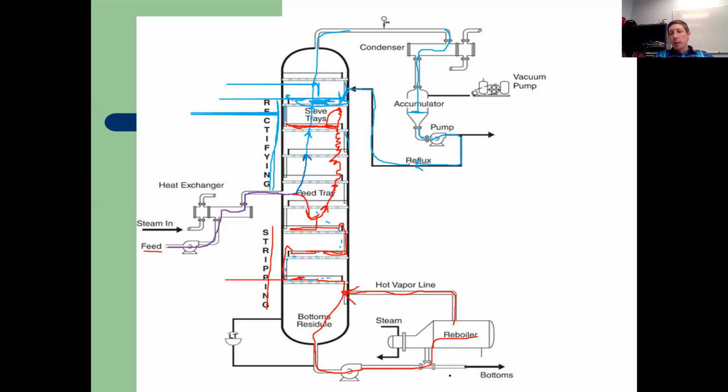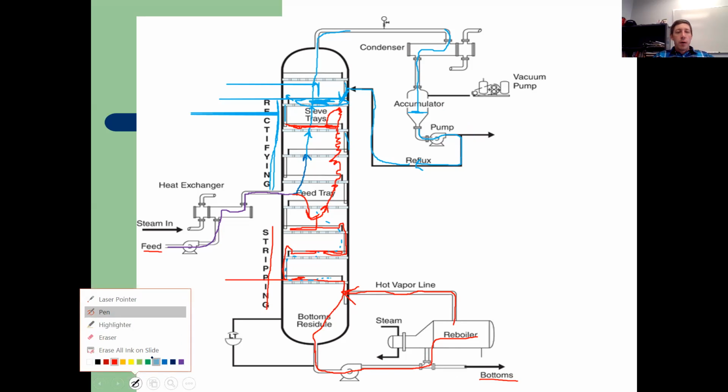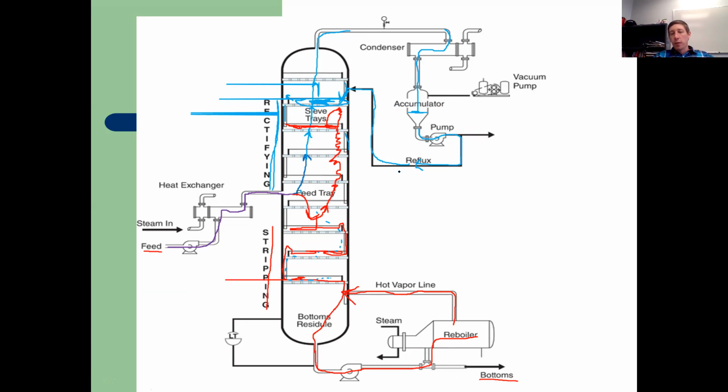Okay. Bottoms product, also called residue. We have tops product, also called distillate. Not all the light material goes back to the reflux line. Somewhere about a third of it actually goes out. We call that distillate. Okay, and so we have one product that goes out here and another product that goes out at the bottom. Generally speaking, this is our high dollar product, and this is our leftovers product. And we can have other products coming out of our system as well. It's not always the case, but generally speaking, that's how we normally have it.